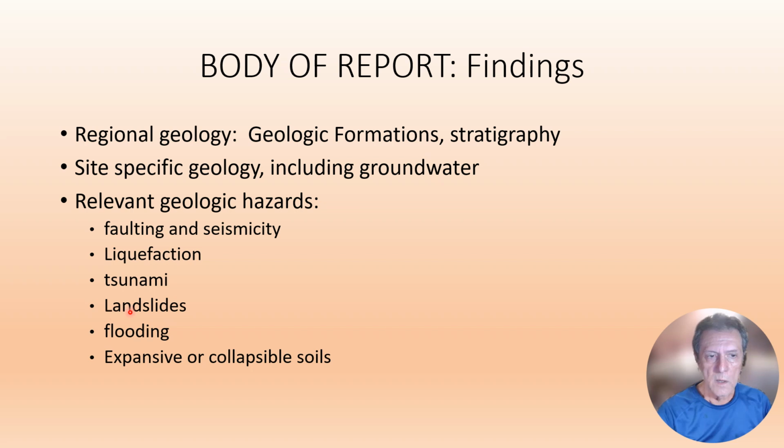On a hilly or mountainous site, are you going to be worried about landslides? If you're next to a river, will flooding be an issue? If you're on top of plastic, stiff, deep clays, is expansion of those clays when they're wetted going to be a problem? Or perhaps you're located on top of wind-blown sediments that are very porous, and if water is introduced, maybe those soils will collapse.